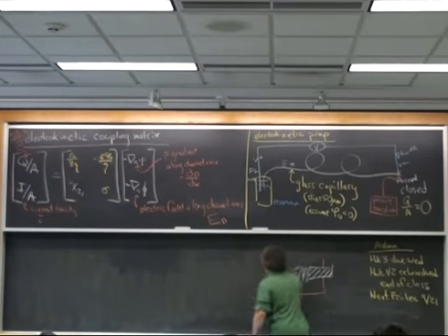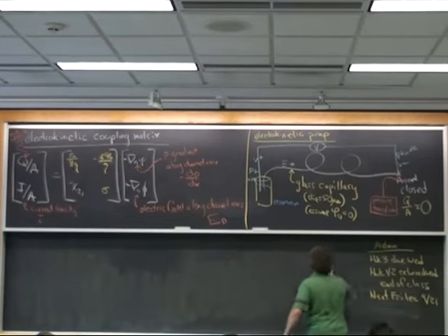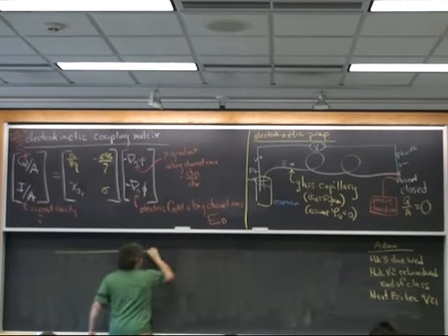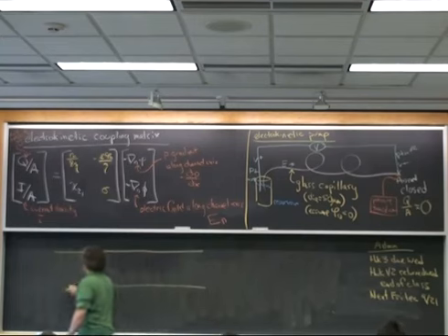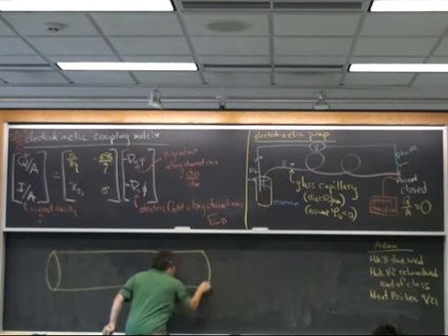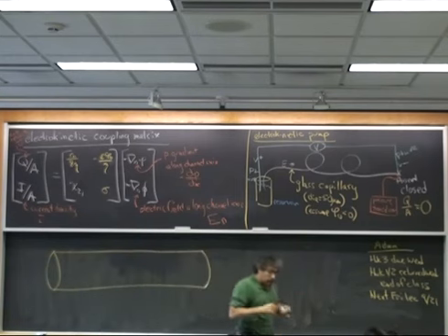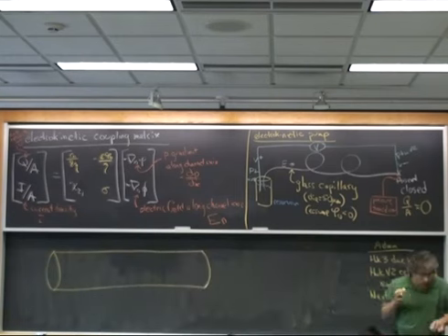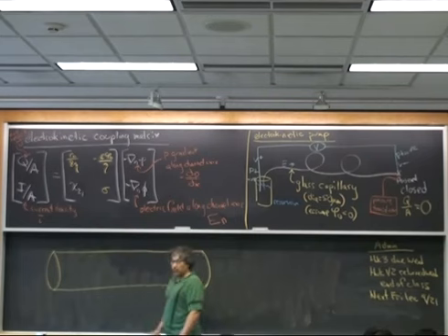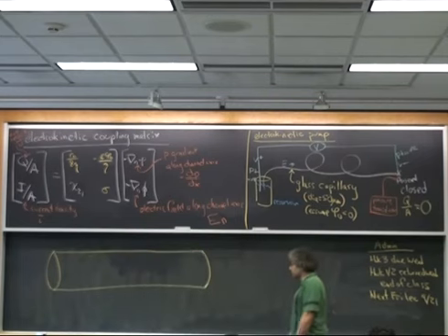Okay, so now let's zoom in. Let's zoom into this channel and see what's going on. In fact, we'll talk about the flow in this channel chronologically. And this chronological description really depends on there being some finite compliance in the system. It turns out realistically, if you connect this system, it always has a finite compliance. And what I'm about to describe typically will require at least a second or two at minimum.